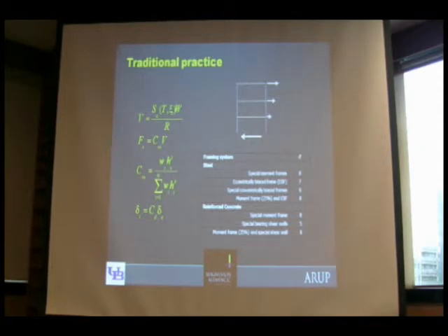So we go through a whole lot of busy work to compute the elastic demands on our framing system for our design event, and then we divide those demands by this response reduction factor, which typically takes on a value of between 4 and 8. Once we have computed this design base shear, we then distribute that force over the height of the structure using a first mode profile, which often takes the form of an inverted triangle.